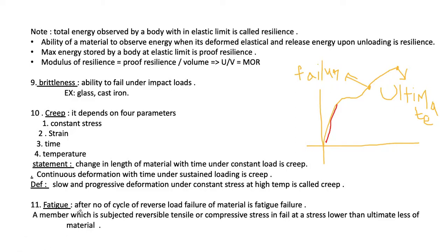Fatigue is failure of a material after a number of cycles of reverse load. If you apply the load a number of times, number of cycles, in reverse, the failure is fatigue failure. We can say that a member subject to reversed tension or compressive stress fails at a stress lower than the ultimate strength of the material.